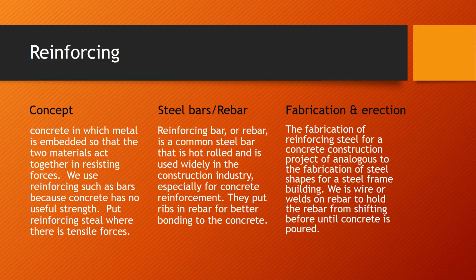Reinforcing. Concept. Reinforced concrete is concrete in which metal is embedded so that the two materials act together in resisting forces. We use reinforcing such as bars because concrete has no useful tensile strength. Put reinforcing steel where there are tensile forces.